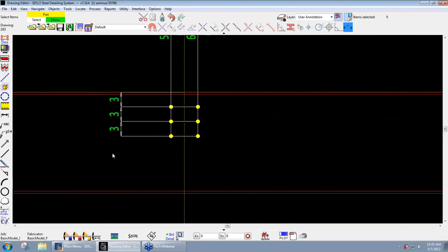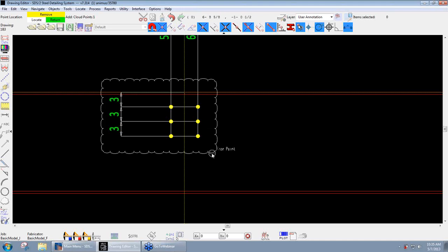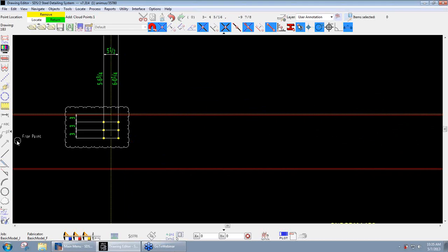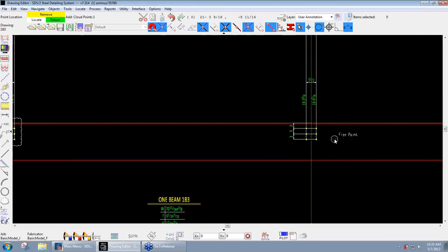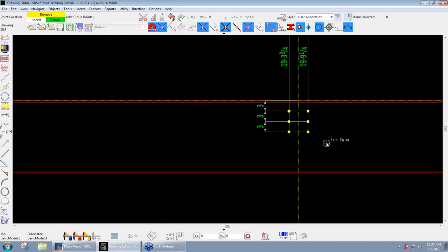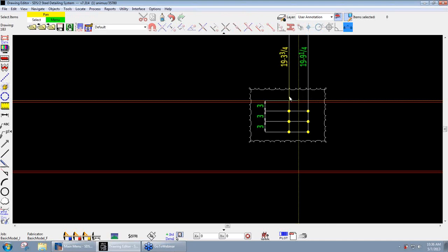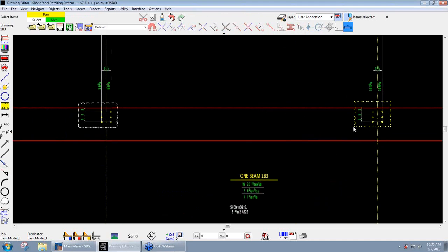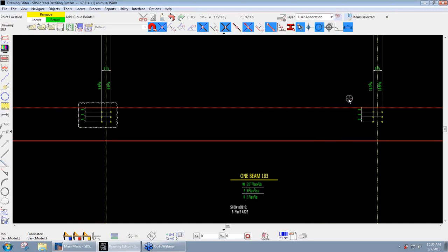The other thing we can do now with clouds, the big change that happened with clouds, is when I do a cloud add, I can now just simply click and drag a square, and that's going to give me a square cloud. So that's really the biggest change with that. When you click and drag that cloud, the direction that you drag matters. Previously that first one I went from left to right, now I'm going from right to left, that inverts the cloud, so it will create that cloud in the different direction. So the big thing with clouds, like I said, is just the click and drag of a square.